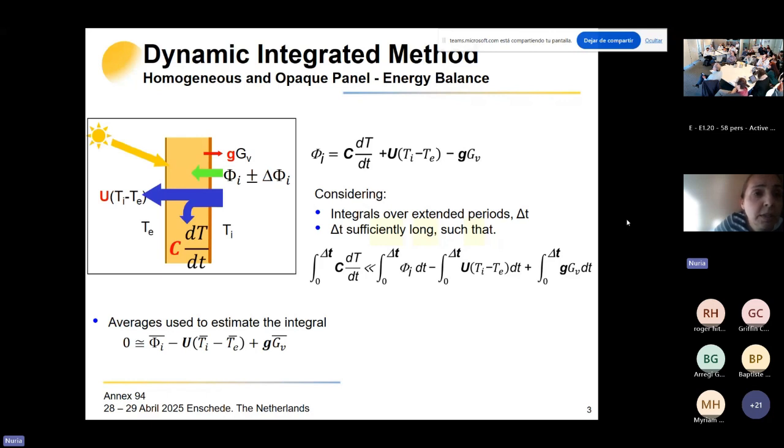The most relevant variables that we have identified are the net heat flux, also the temperature difference between the interior and the exterior of the wall, which is going to drive these heat losses through this sample wall. And also the thermal accumulation that is going to be indicated by the changes in the sample temperature.